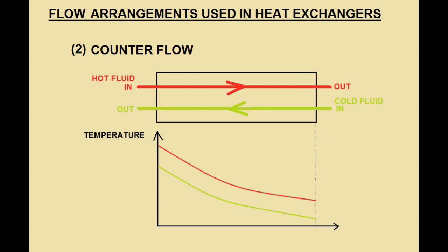Counterflow arrangement. In the counterflow arrangement, the fluids enter at opposite ends, flow in opposite directions, and leave at opposite ends. Some advantages are there. More uniform temperature difference between the two liquids minimizes the thermal stresses throughout the heat exchanger.